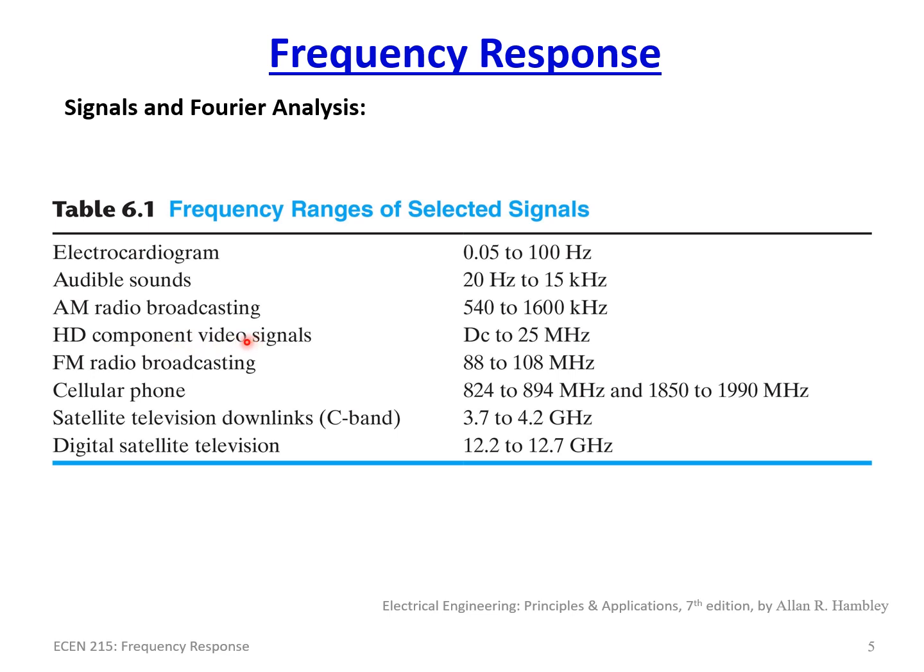Component video signals for high definition is anything from a DC offset all the way to 25 megahertz. Frequency modulated radio broadcasting. Again, this is not a signals class, but radio that is transmitted to, like, your car or whatever, uses two different techniques. One's amplitude modulated and one's frequency modulated. Modulated means you're doing one type of transform to the signal, with the actual signal that you want, in this case audio, being transformed to a higher frequency to transmit it.